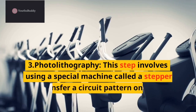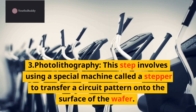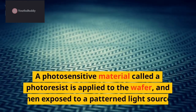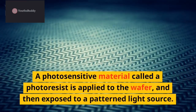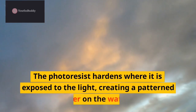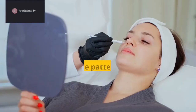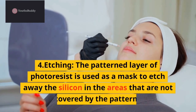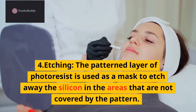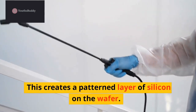3. Photolithography. This step involves using a special machine called a stepper to transfer a circuit pattern onto the surface of the wafer. A photosensitive material called a photoresist is applied to the wafer, and then exposed to a patterned light source. The photoresist hardens where it is exposed to the light, creating a patterned layer on the wafer. 4. Etching. The patterned layer of photoresist is used as a mask to etch away the silicon in the areas that are not covered by the pattern. This creates a patterned layer of silicon on the wafer.